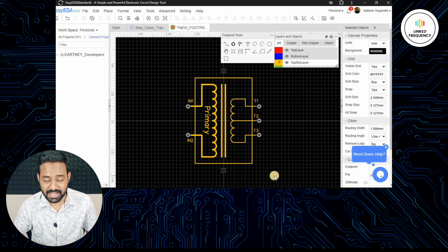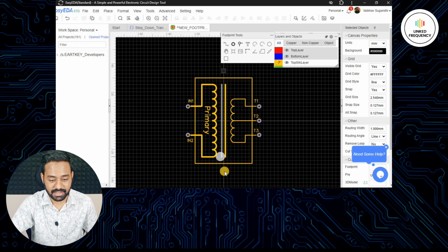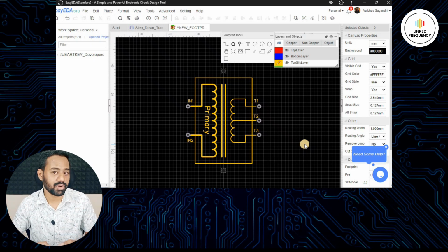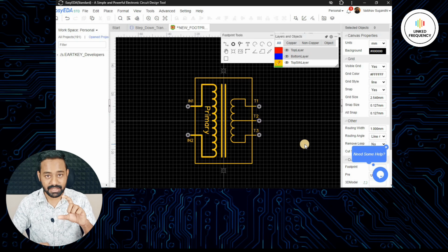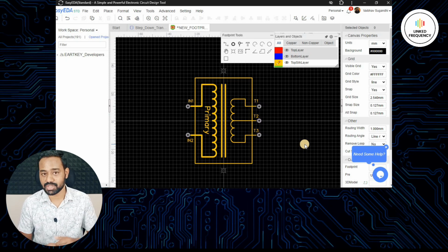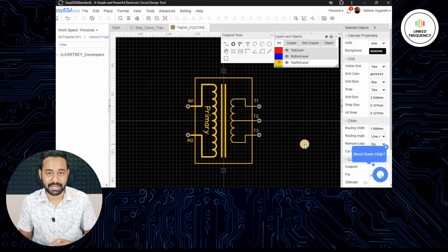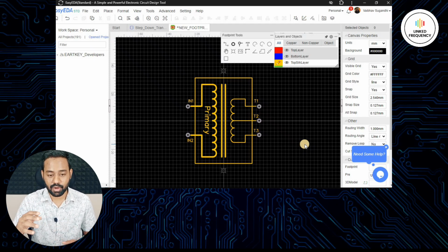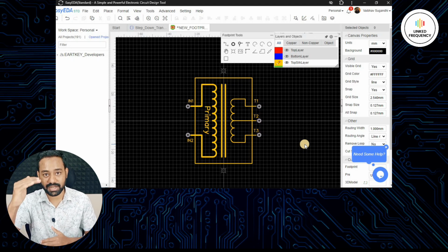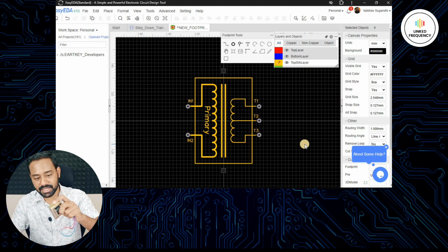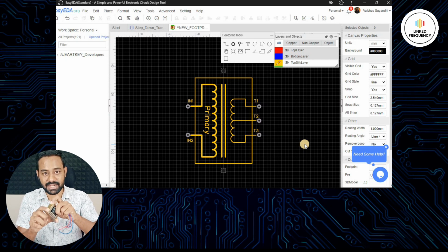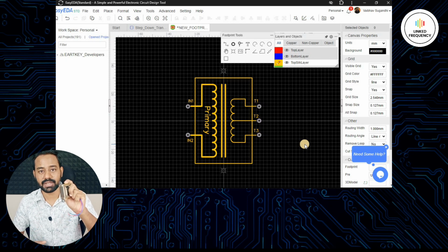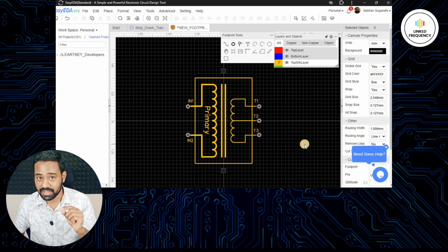And also you can notice that the mounting holes of this entire transformer is completely outside the body of the transformer. I have considered the body of the transformer as a 60 mm height and width-wise 40 mm as measured on the physical transformer in hand. Now, using these two data, I have created a placement of those two mounting holes outside the body of the transformer, because physically it is outside only, not inside the transformer. And even though it is attached to the body, but it is outside the body of the transformer. Considering that is very important.